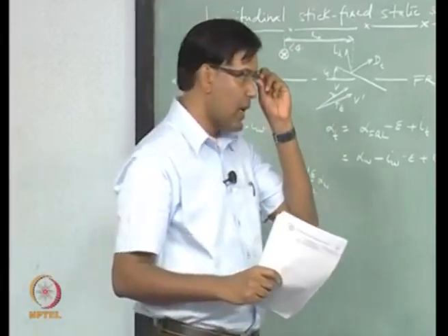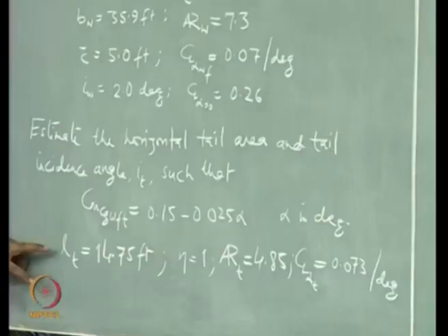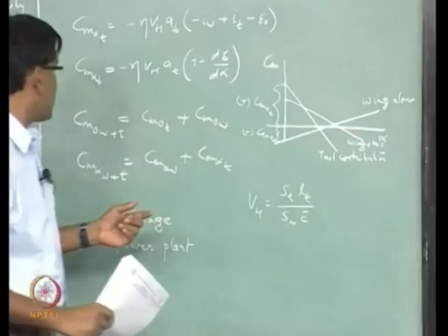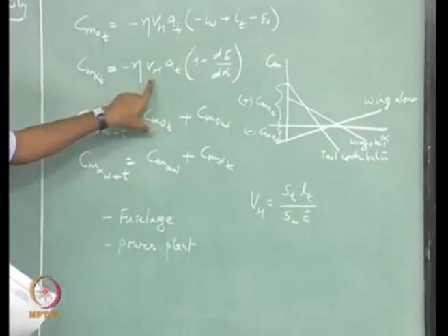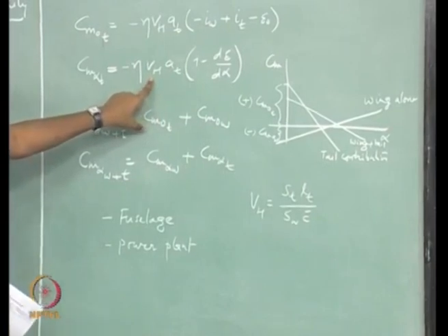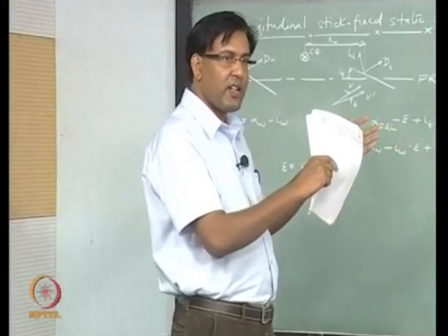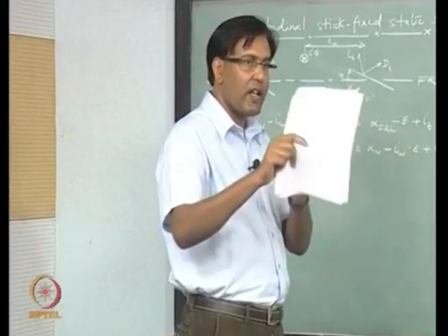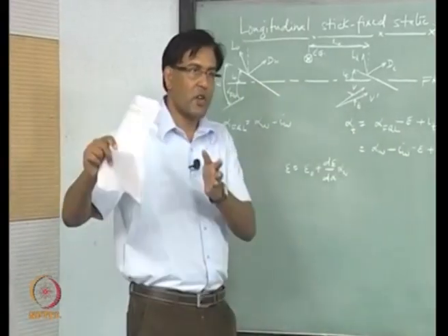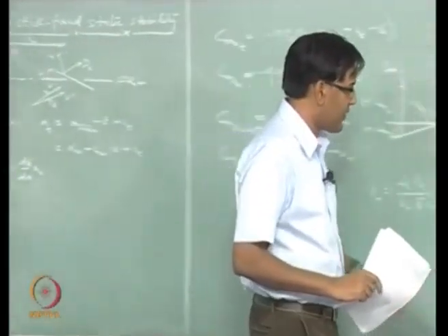That is one condition, and this is also going to affect the stability through this term, right. And it's also going to be affected by what is the overall length of your aircraft, right. Once you have placed your wing at some location, you only have only so much space left where you can place your tail. All right.